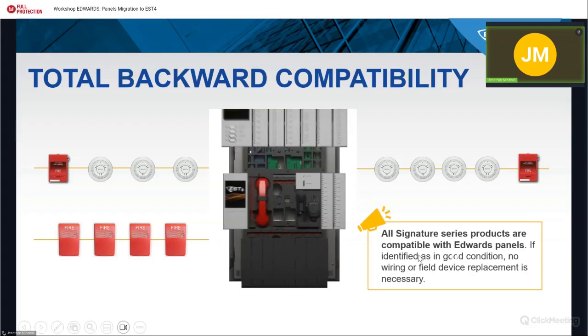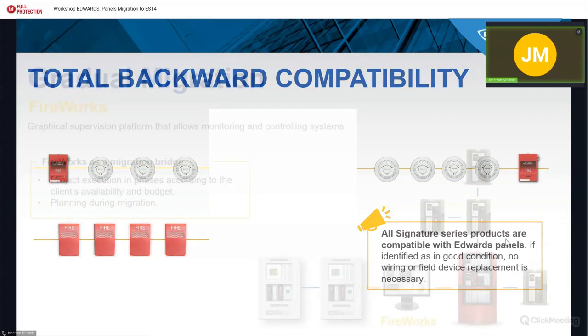I want to add something. When you have a project with the EST3 and you have power supplies, remote power supplies, we always recommend to the integrator that you maybe also change the power supply. If you have a project more than 10 years old, I recommend that you also change the power supplies. I want to add that.